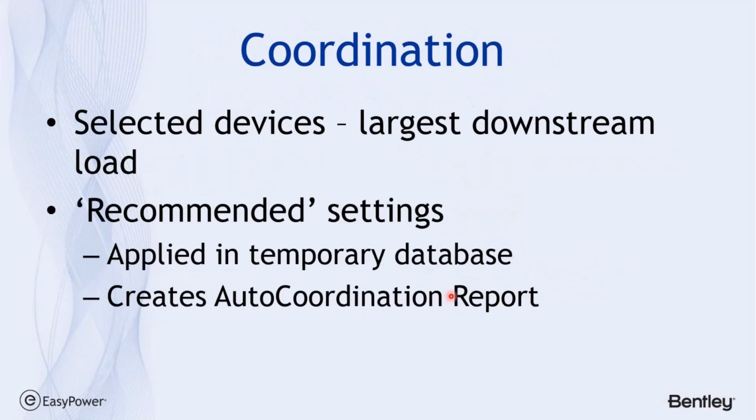I'll try to show where that's the case and be able to amplify that when we get to it. Now, coordination, basically, and this is a good exercise to prove to yourself, for a particular bus, to be able to coordinate that bus itself, you need to coordinate against the largest downstream load. And the point I would want to make is once we've coordinated with the largest load, then the smaller loads on that bus will by default be coordinated with our setup upstream.